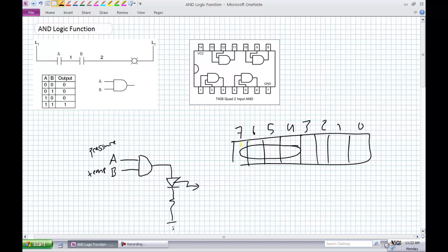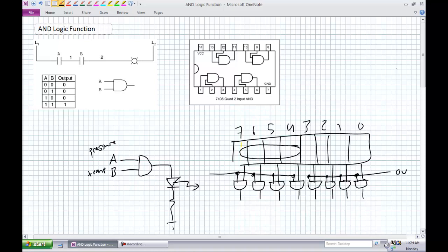Think of our gatekeeper strategy. Let's have 8 AND gates. I'm going to go ahead and draw that. Take the outputs of those registers 0 through 7, assign to one of the inputs of the AND gate, and we're going to go ahead and we want to erase 0, 1, 2, and 3, but leave what's in 4, 5, 6, and 7. How do we erase something with an AND gate? Put a 0 on that one's input, 0 on that one's input, 0. So those are all two independent AND gates. Put 0 volts right there. Put a logical 1 on there, or 5 volts on that one.